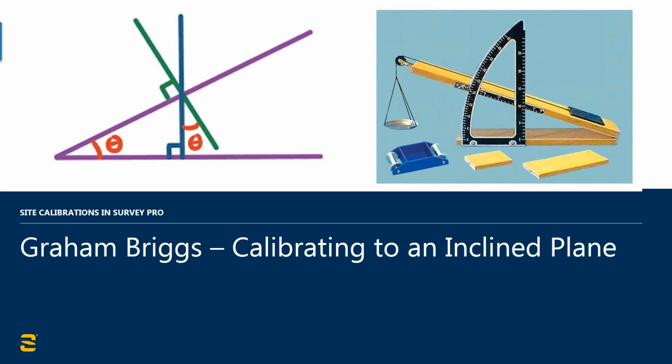Thanks, Joe. So really what we're talking about here is the vertical component of the calibration. You remember in the little flow chart we showed you, it showed the vertical part clearly coming off and being handled differently from the horizontal part. The example that Joe showed with the project area was really that top-down plan view, and hopefully you can picture in your mind that the horizontal calibration is really nothing more than a similarity transform. We translate, we rotate, and we potentially scale a tiny bit, one set of coordinates XY to another set of coordinates XY. The vertical is completely different though.